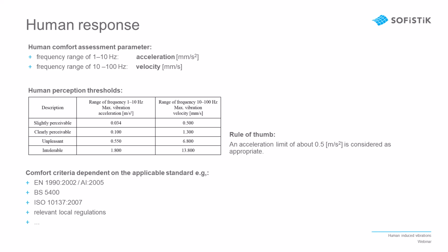Significant exceedance of these threshold values may result in user discomfort and even fear and reluctance to use the structure. Just because an insignificant utilization ratio has been reached does not mean that the deformation and vibration of the structure is not off-putting. So it is a serious matter for the designers to consider.